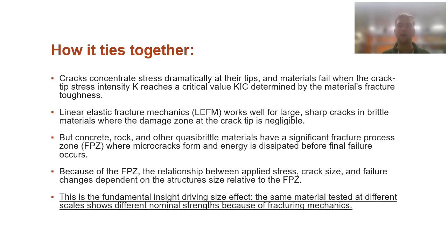So let's tie it all together. We just learned a lot about linear elastic fracture mechanics, quasi-brittle fracture mechanics, and we hinted at a little bit of the size effect. Well, I think that some of the big takeaways here were that cracks in LEFM concentrate stress at the tip, and they fail when stress intensity reaches that fracture toughness.